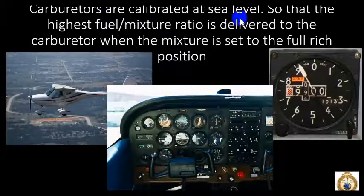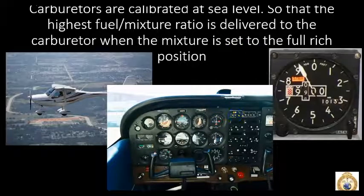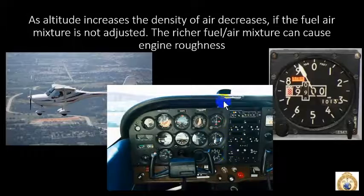These carburetors are calibrated at sea level so that the highest fuel air mixture is delivered to the carburetor when the mixture is set to full rich. And that will be when this is all the way into the panel, not hanging out. You wouldn't see any shiny part of that knob. As altitude increases, density of air decreases. And if the fuel air mixture is not adjusted, then a richer fuel air mixture can cause engine roughness. So as we get up higher above 3,000 feet, typically we have to start pulling this out.